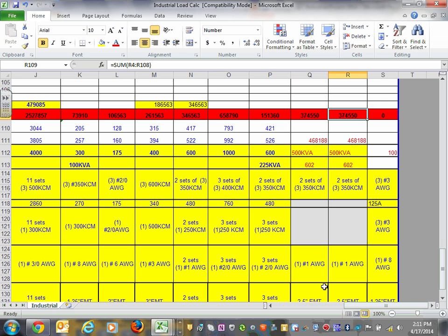utilities do. I used to do medium voltage. When I was working for SCH, at that time I was working for utilities, we used to take this calculation and we call it, and utilities still call it, architectural calculation. All that stuff that we've just done, they call it architectural calculation, not even engineering. And then cut it by half. So a 4,000 amp switchgear, a 2,000 amp transformer sitting there outside for you.